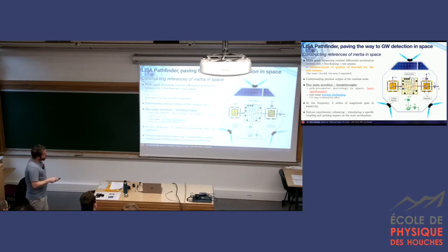So usually there is a golden wire that connects the test mass to a mass, to evacuate the electrostatic charge on the spacecraft. Because you have this mechanical contact at low frequency, it's damping the test mass and making it deviate from pure free fall. And you were basically losing sensitivity, adding some acceleration noise.